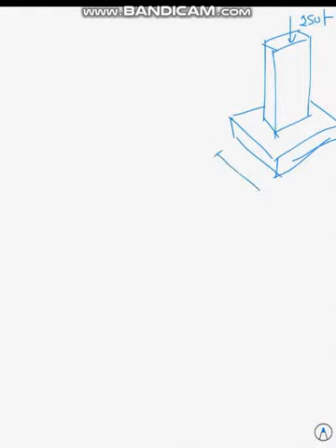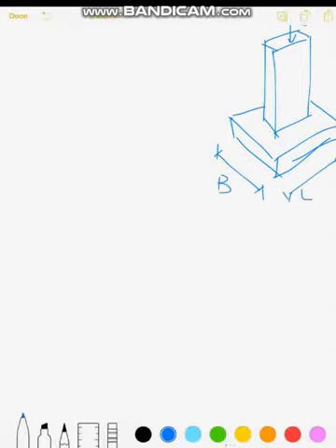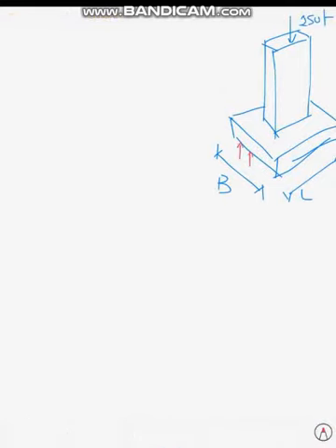So I need to first of all determine the width and length for this foundation to ensure what? To ensure that the contact stress under the foundation is less than the allowable net bearing capacity. I need to ensure that the contact stress between the footing and the underlying soil is less than or equal to the allowable net bearing capacity, to ensure that the column load is transmitted safely to the underlying soil without having excessive settlement or bearing capacity failure, as we have already discussed the two main conditions for proper design of shallow foundations. Okay, this is ensured by determining the required area.